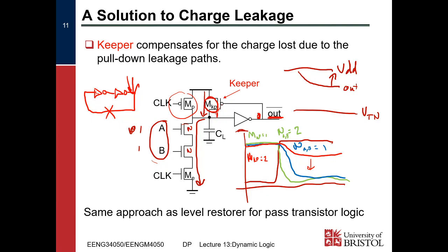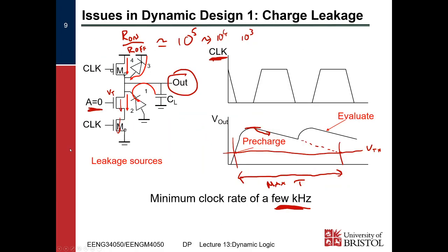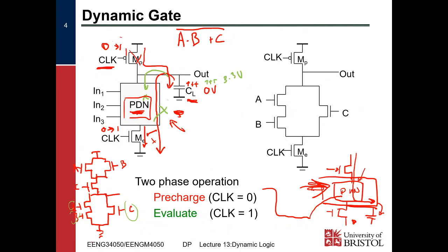Dynamic logic, question was, is domino ratioed then? Dynamic logic, if we put a keeper in it, is ratioed, right? And we need to be very careful of our ratios. If we do not put that keeper transistor there, if we just design it like we did here without a keeper transistor, it doesn't become ratioed, but at the same time we have a minimum clock frequency if we don't have the keeper transistor, right? So it's a design trade-off.